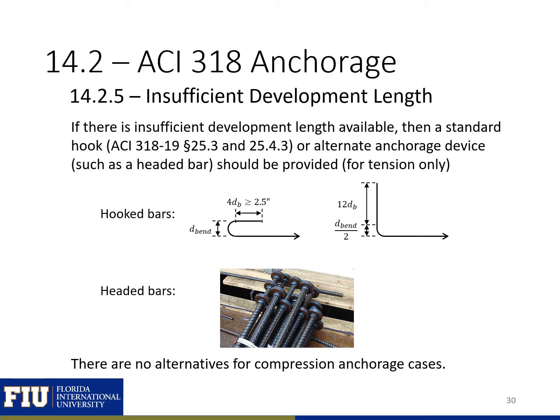If there is an insufficient development length available for a straight bar, then typically you'll either use a hooked bar with a 180 or 90 degree hook, or a headed bar where you can have a mechanical head on the end of these bars.